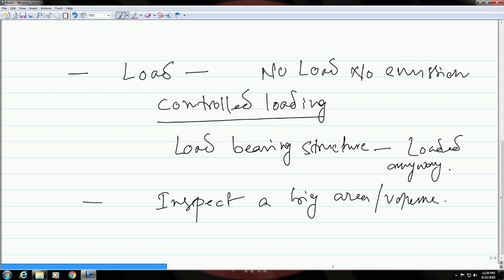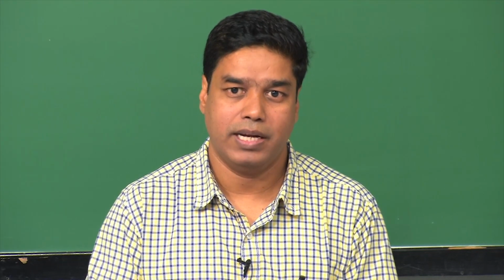Even if you have a very big structure or a very big area to be inspected, that can be done in a single examination by placing a number of sensors at different locations where you think there could be a potential source of damage, which could lead to acoustic emission events.